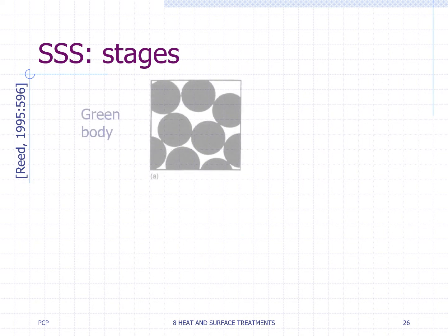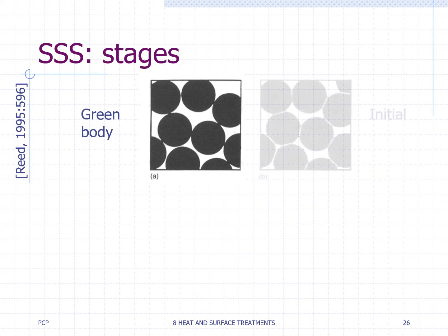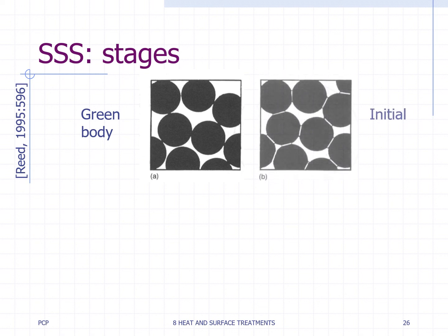Microstructural changes in the stages of solid-state sintering are observed here. Initial: surface smoothing of particles, grain boundaries form, neck growth, rounding of interconnected open pores. Porosity decreases less than 12%.